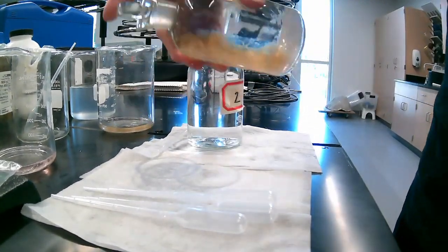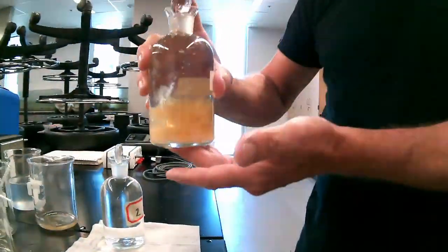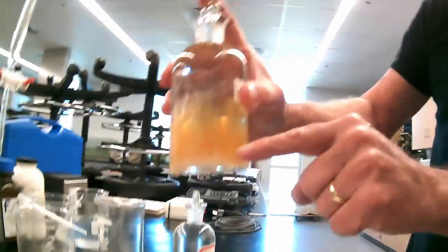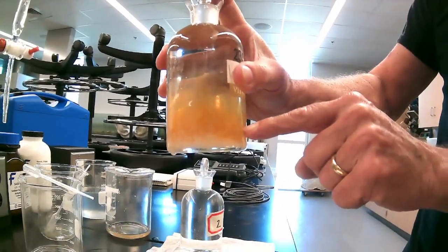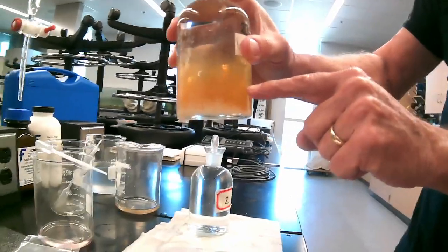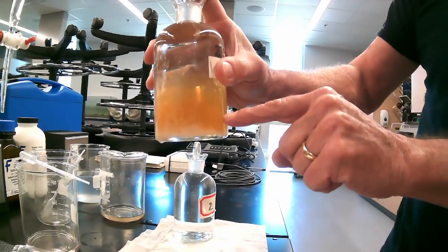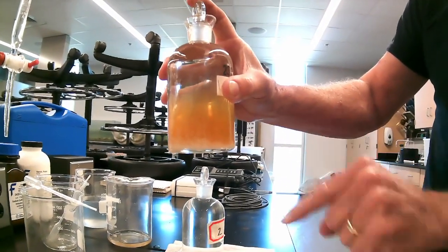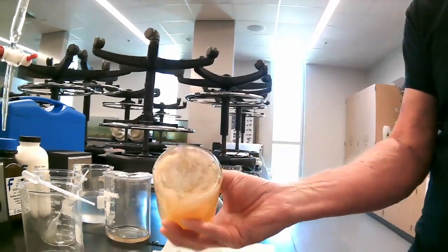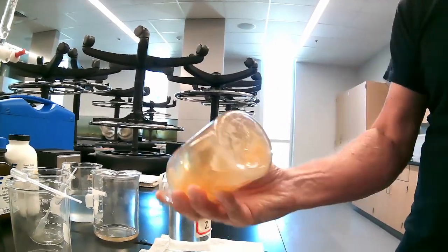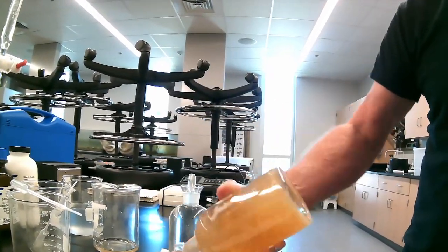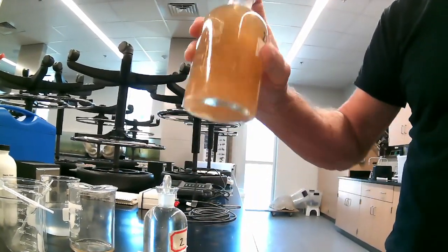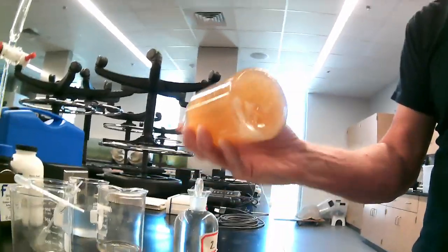Empty the excess off. And we roll the bottle, we never shake the bottle. What do you see in there? The orange flocculant, we refer to that as flocculant because it looks like a cloud in there. That is the oxygen bound up right now from the potassium iodide and manganese sulfate reaction. So we roll that bottle around. The bottles are built so that they roll the flocculant around to try and pick up as much of the oxygen as we can.